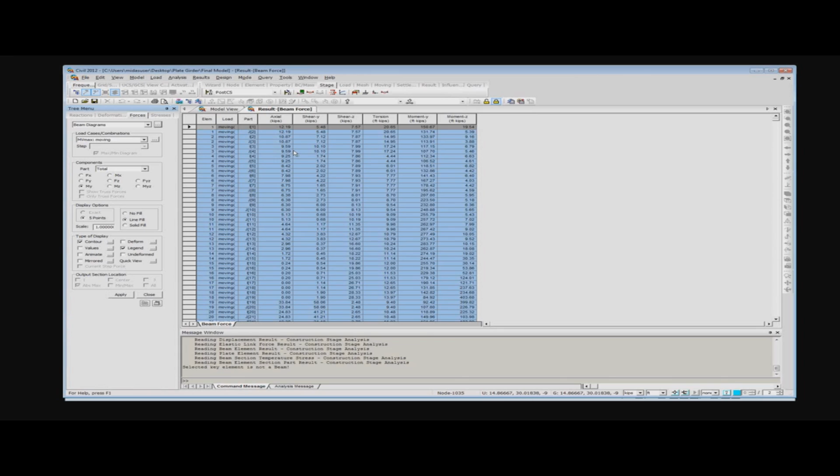In the analysis control, I activated the option to get the result of concurrent forces for the moving load analysis. Which means whenever you get the maximum bending moment in one section, one element, what would be the corresponding axial forces on that element? So for that reason, you have all these here, and then you can sort this based on ascending or descending as you want.